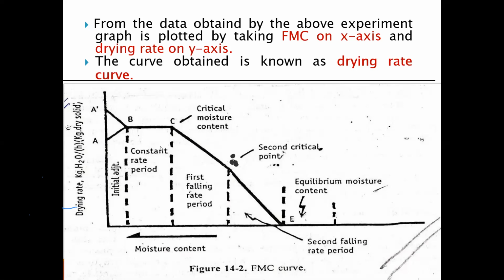In this case the moisture completely begins to evaporate. At the same time, the moisture is coming from inside the solids to the surface. Understand it? The moisture coming from the internal solids is called diffusion. So in this case, the rate of diffusion is equal to the rate of evaporation. Understand it? Rate of diffusion equals rate of evaporation.